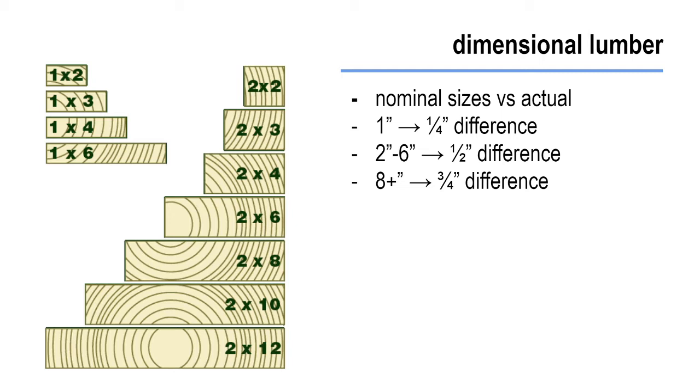And as the moisture leaves the piece of wood while it's sitting there drying after it got cut, it's going to slowly shrink down as that moisture releases. And so that's also where that little extra amount comes out of. If the number in that nominal amount is 1, it's usually just about 1/4 of an inch smaller.